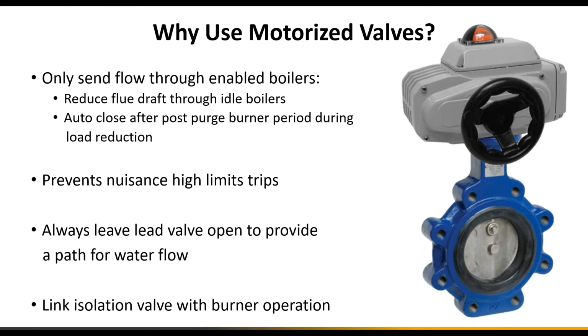Keep in mind that with high turndown boilers, these boilers will typically run virtually continuously. You may have automatic rotation, so that on a daily or weekly basis, you designate another boiler to become the lead. But once the system's up and running, with the high turndown, the boiler will hardly ever shut down unless we get into summer mode conditions.